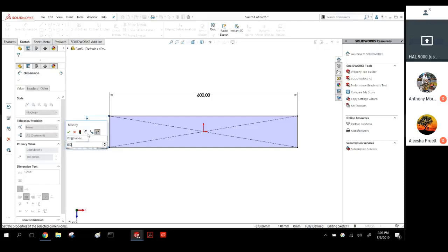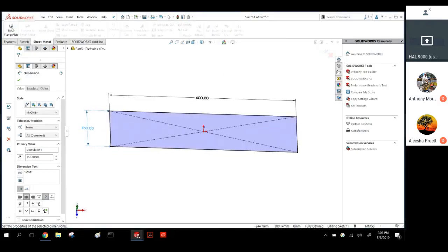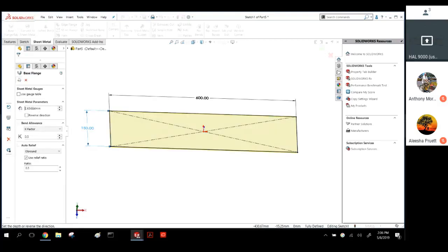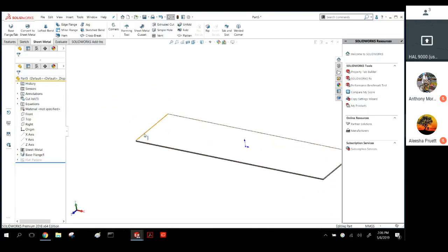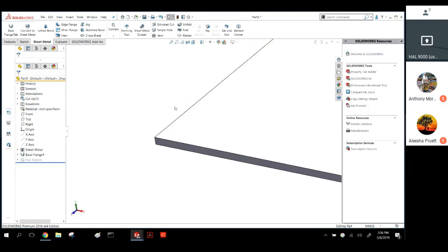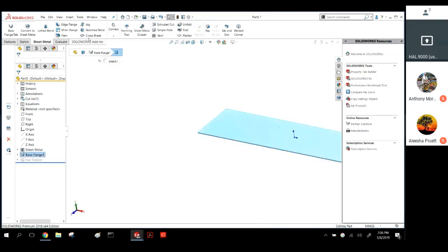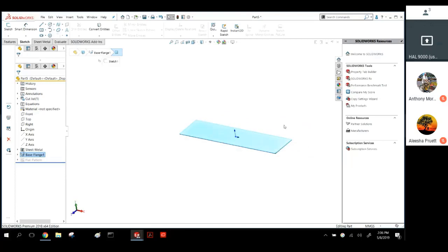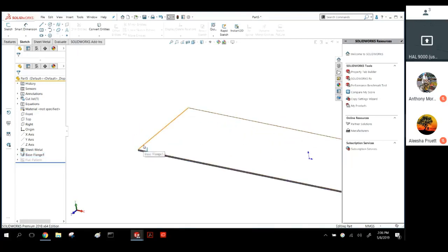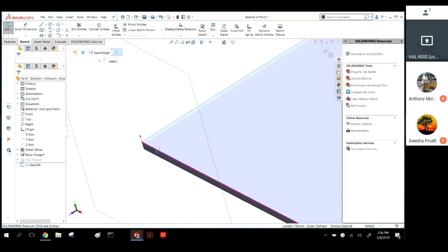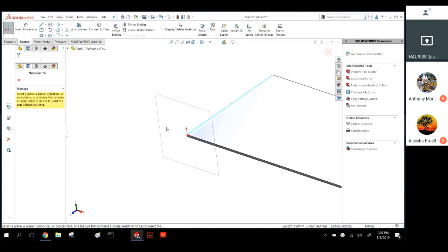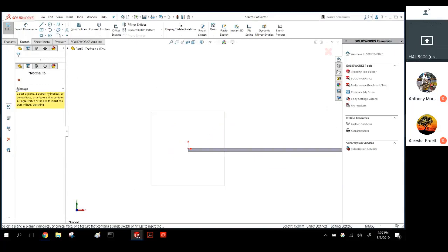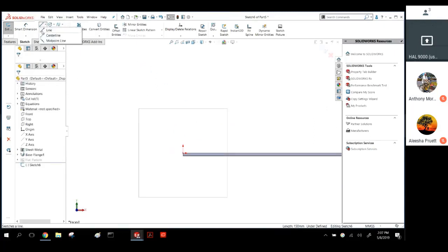But now, typically the only thing I'll use the miter flange for is an operation like this. First, I'm going to create just a flat piece of metal. Got the sheet metal gauge, got my flat pattern, all that sort of stuff. There's nothing to flatten out right now. There is a trick when you're sketching. If you pick a face and you choose to sketch, it starts using that face as a sketch plane. But if you select an edge and you hit your sketch tool, what it does is it places a plane on the end of that edge, perpendicular to that edge, at whatever the closest endpoint you selected was. And so I can draw this shape right on the end of this piece of metal.